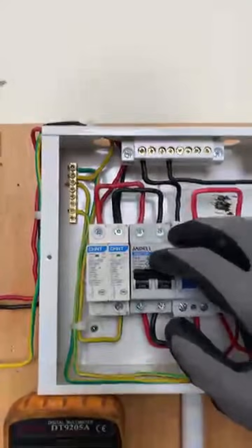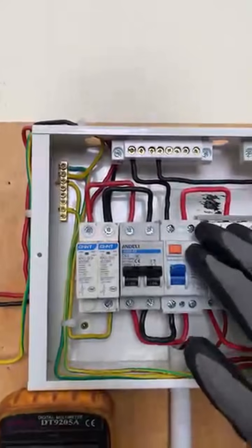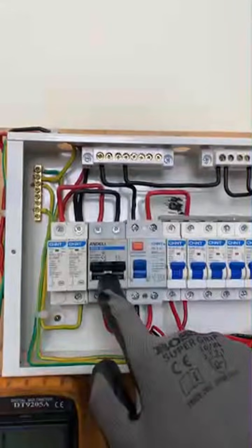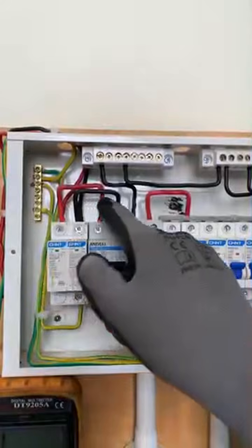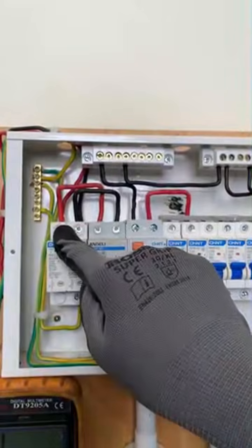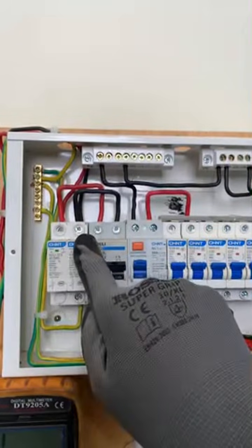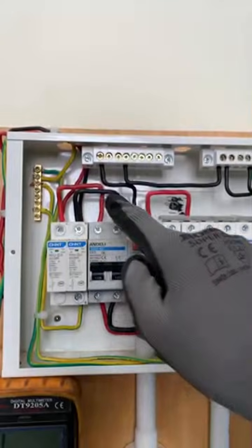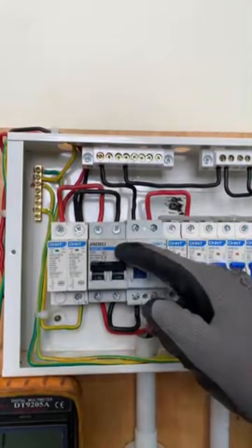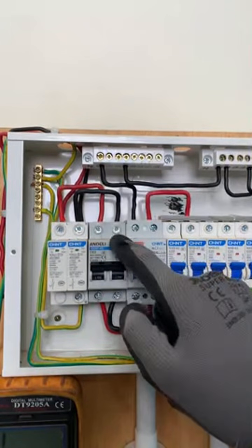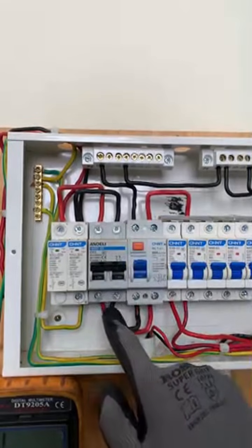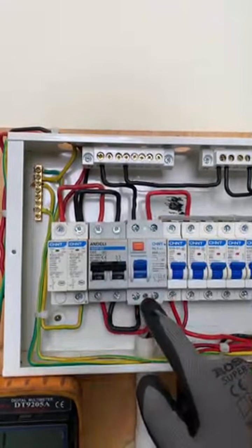I've come prepared, armed with the gloves. Remember, this circuit is on. So from this point here, we have, first of all, electricity flowing in through this point, right? So at this point, we have L and N, and it is tapped to the top part of the MCB, sorry, miniature circuit breaker. And then the output here is fed to the RCCB.